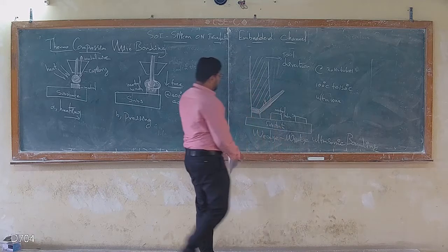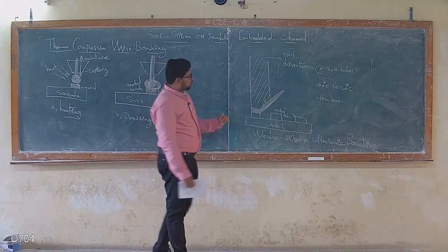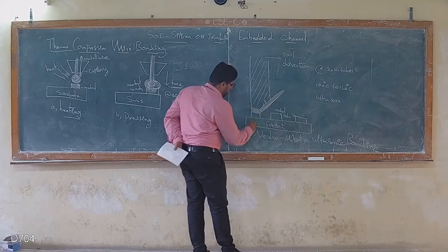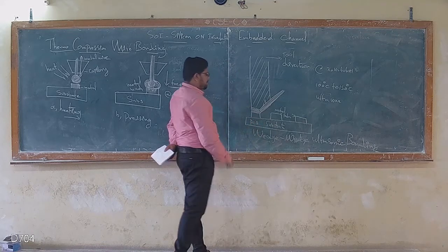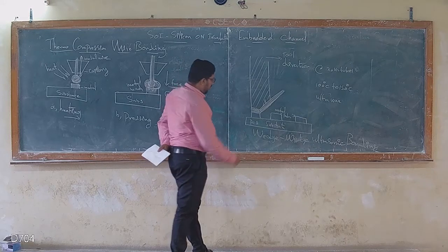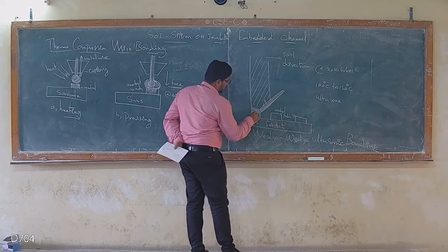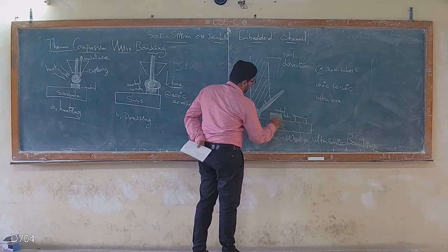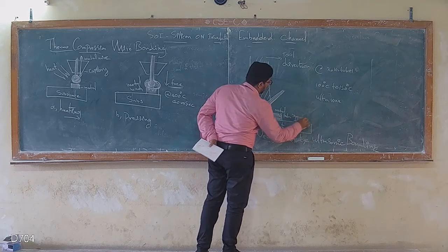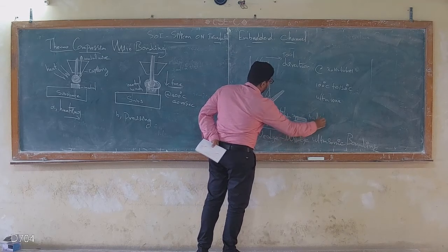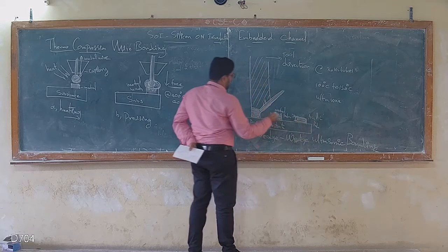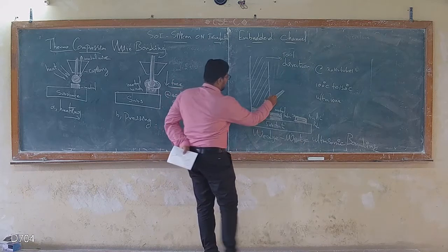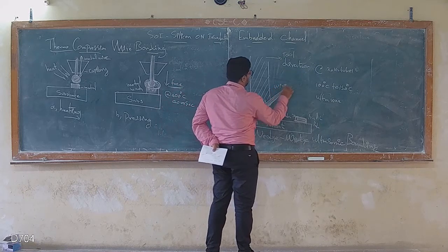So here you understand this is called wedge ultrasonic bonding, right? It has a substrate. It may be a PCB, or it may be a silicon substrate, and it has metal patches like this. There is a metal patch. It could be a metal, either palladium, aluminum, or even gold, Au, Al, or palladium, anything. So this is the tool which will apply a wire. This is the wire I'm going to use to make the bond.